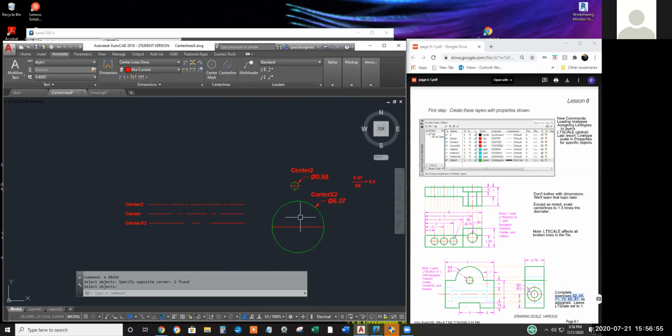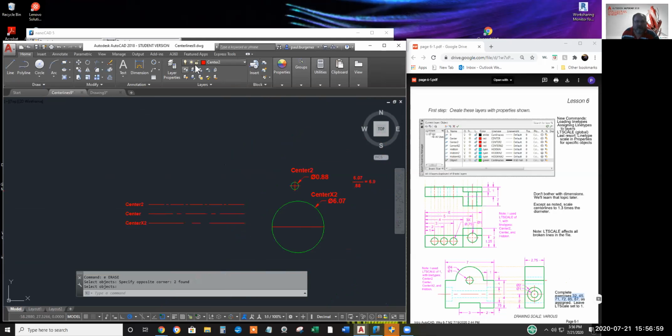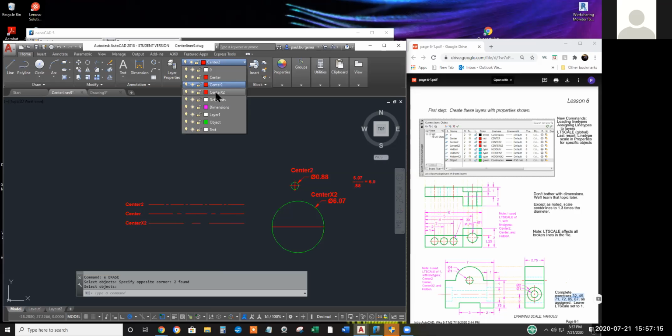Now consider, Daniel, using multiple layers, and if you're getting multiple short lines, maybe change the line type of your layer. You with me? I'm still trying to understand the whole concept of the line type of the layer and how scale mixes in with it. It seems like there's a couple variables that I'm not understanding how exactly it works.